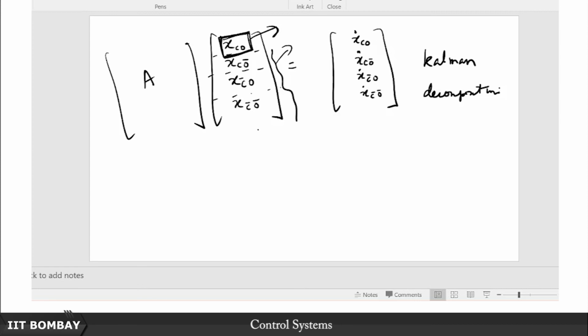Then in a multivariable controls course you will also learn about what zeros are. You will see that even in a matrix, each of whose entries is a transfer function, probably a rational function, you can still end up with a situation where each of those individual entries has certain zeros, but the overall system, the MIMO system, the multi-input multi-output system, can have no zeros. So you need to be very careful about what the definition of a zero is in such a case.